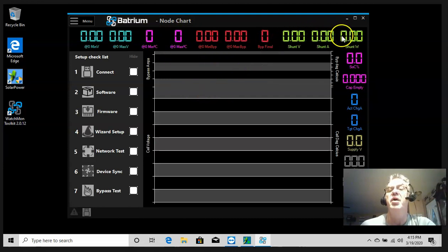It gives you a lot of information, and then of course this system is set up to keep those cells balanced, and that way when the energy is being used, they'll run down together and then be charged up together. And if they're a little bit off, then this system will actually keep them balanced. So it'll rebalance the 7 cells, because there's going to be 7 in series, and it's going to be 150 cells in each brick.